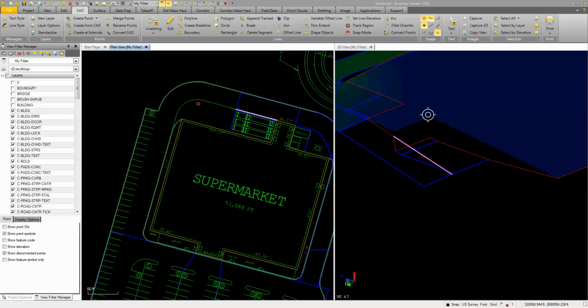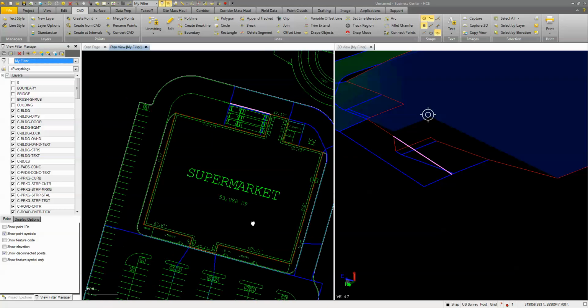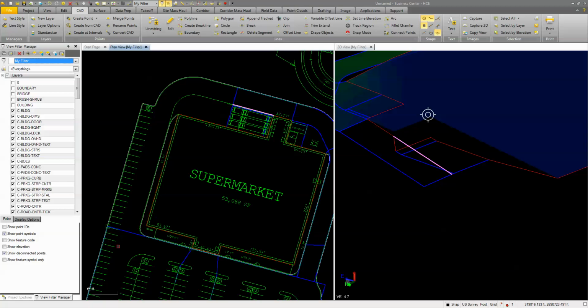So what we'll do now is we'll finish up this upper side of the parking lot. Similar to the other side over here, what we want to do is drain some of this way. We want to drain some of it this way to this low spot over here. So we've got our 1% going this way, we've got our 2% going that way, so we're going to try to match something close to that.